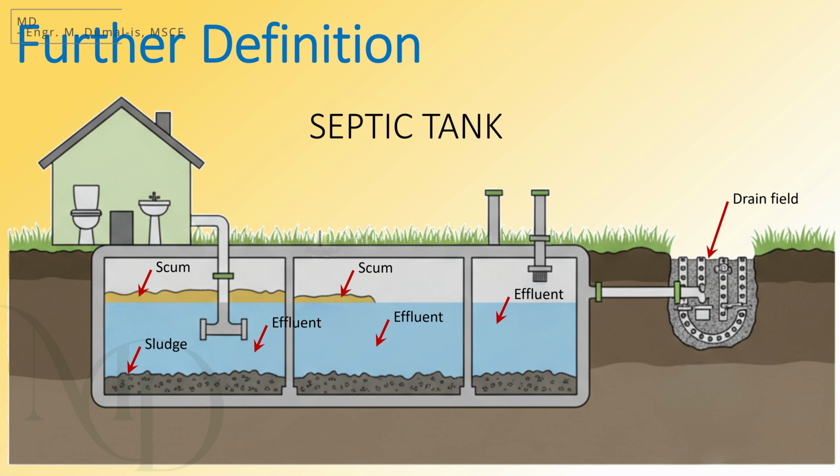Overall, the septic tank holds wastewater long enough for solids to settle and for oils and grease to rise. This separation allows the liquid effluent to flow onward. A well-designed tank usually provides around 2 days of retention time for this settling process to occur.